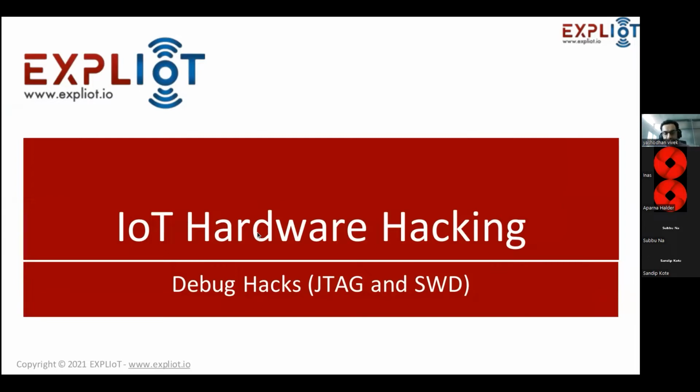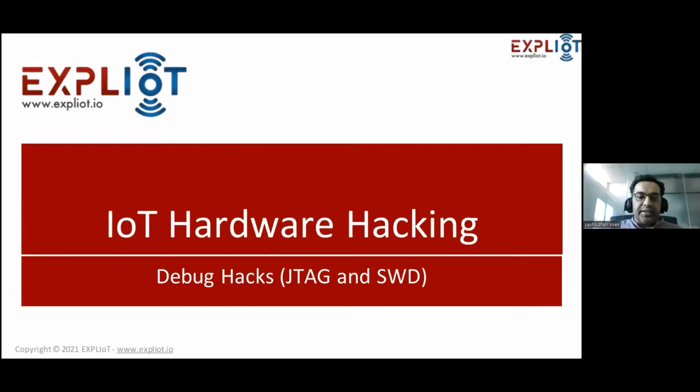I know whoever is working in this domain of embedded system development, when you go for debugging, JTAG or SWD is really a pain at times. Today's agenda: though we use it for debugging or possibly programming your firmware to your microcontroller, there are certain security issues where, if people get physical access to your device, they can get into some of the important registers or the firmware of your microcontroller as well. So today's agenda is to discuss the JTAG and SWD attacks.